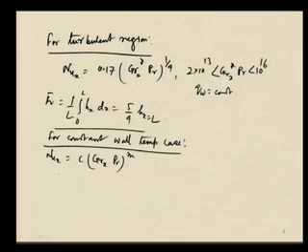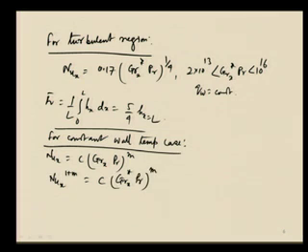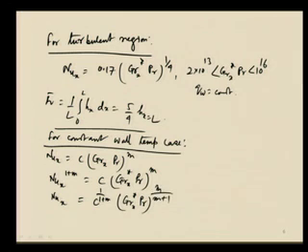Now, if we multiply both the sides by Nusselt to the power m, then we get Nusselt x to the power 1 plus m equals C into Grashof x star, into Prandtl to the power m. Then if I write again, Nusselt x is equal to C to the power 1 by 1 plus m, into Grashof x star Prandtl whole to the power m by m plus 1, whatever you say.